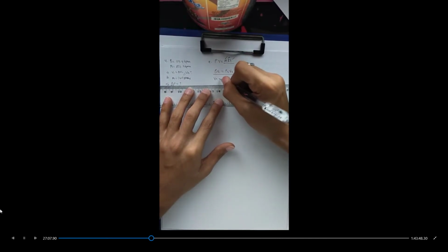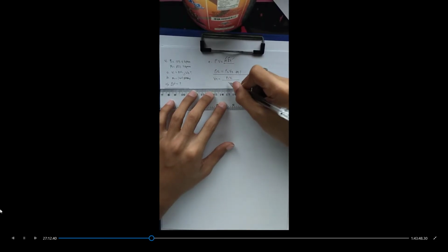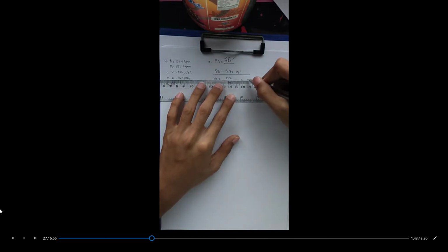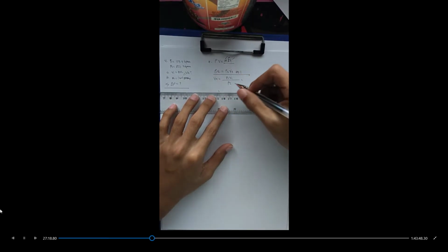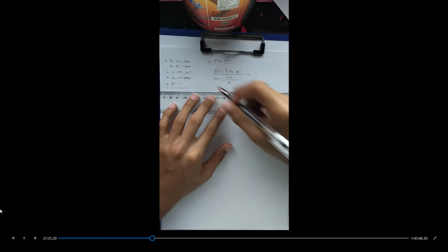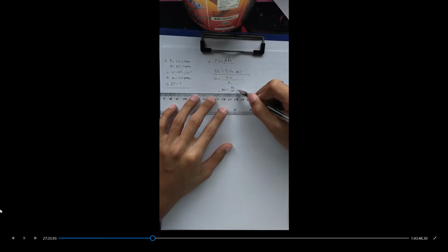So solving for volume 2 is equivalent to pressure 1 volume 1 divided by pressure 2, and just like that, or by substituting the values, pressure 2 is 827.2 kilopascal absolute. By transforming this to its simpler form, kilopascals is written as kilonewton per meter squared, multiplied by our volume 1, which is 80 liters. So we need to convert this one first.